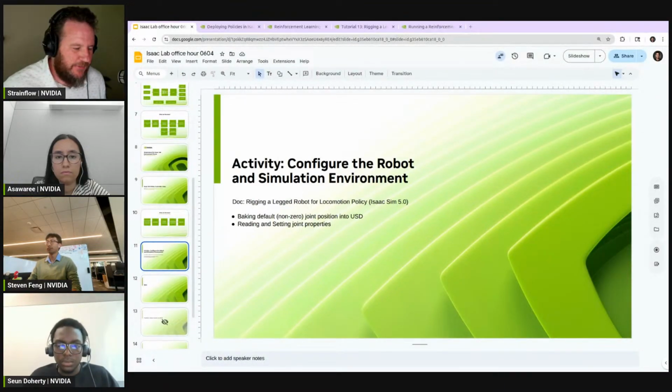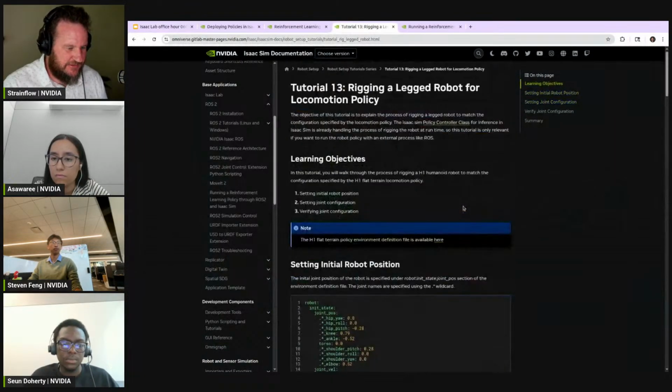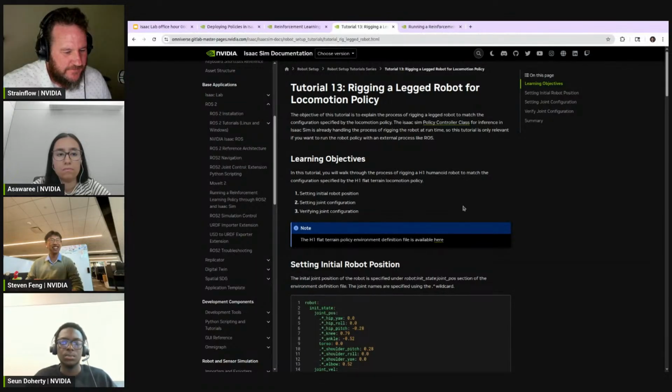So to recap, you basically open the robot, add that fixed joint so that it doesn't fall when you start running the simulation, and then you could hand set each of those joint positions, run the simulation so that it moves to those positions, uncheck that box and stop, and then you could delete that fixed joint. For sure, yeah. Great summary, thank you.